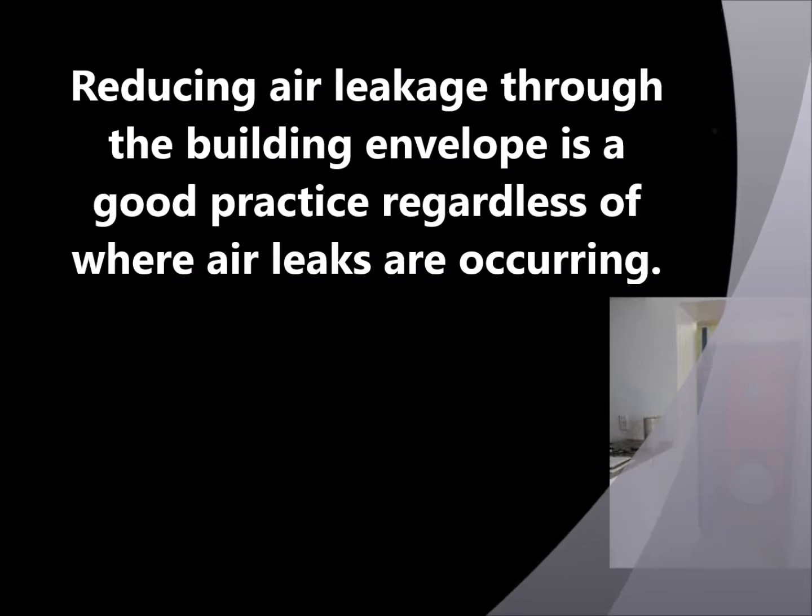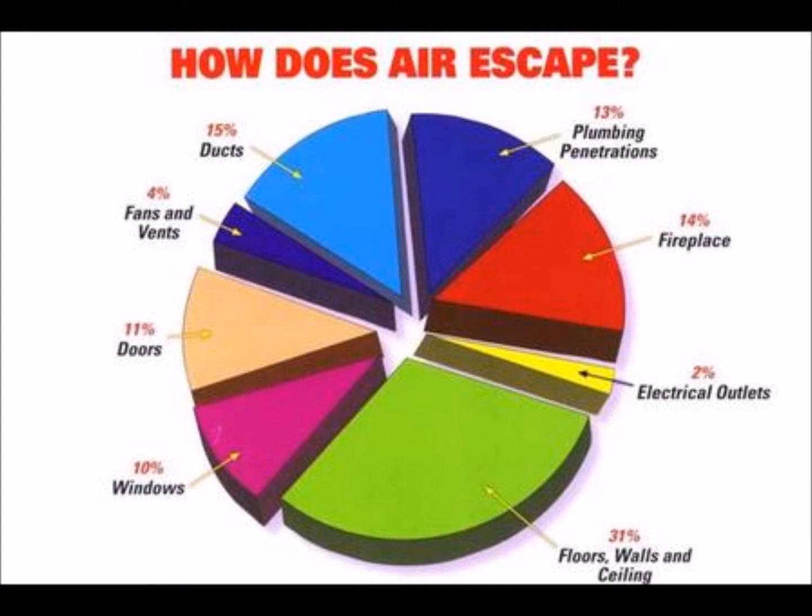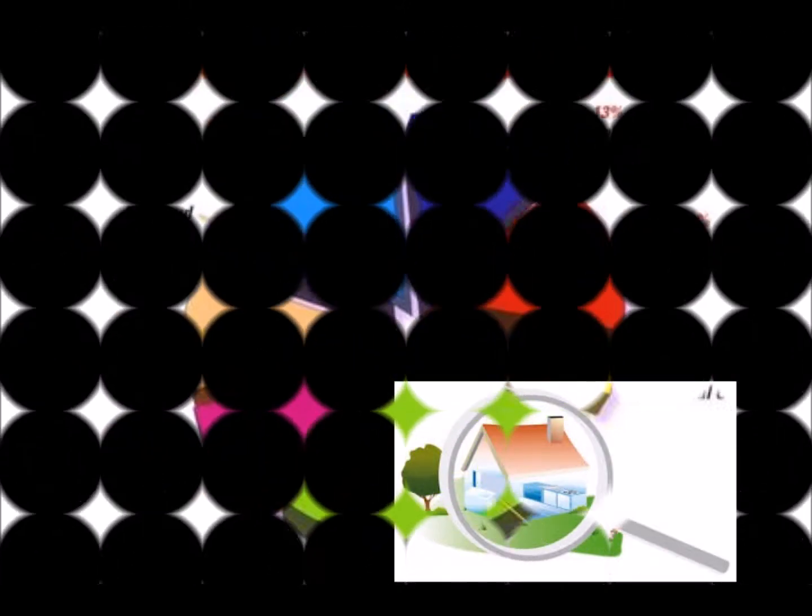Appropriate air barrier materials include some panel products, membranes, and other coatings that have low air permeability. Examples of air barriers include spray polyurethane foams, gypsum wallboard, building wraps, poly foam boards, and exterior wood structural panels or sheathing. Seams and laps in these products must be sealed. Examples of products that might be considered too air permeable to serve as an air barrier include fiberboard, expanded poly insulation, glass fiber insulation, and tarred felt paper.